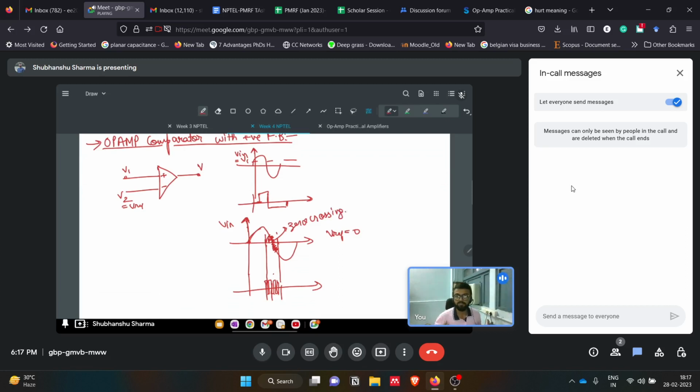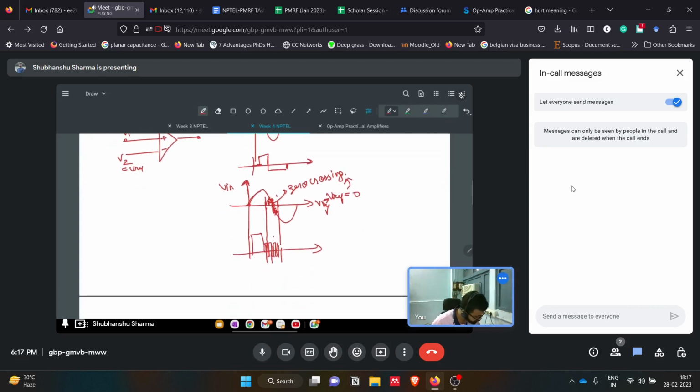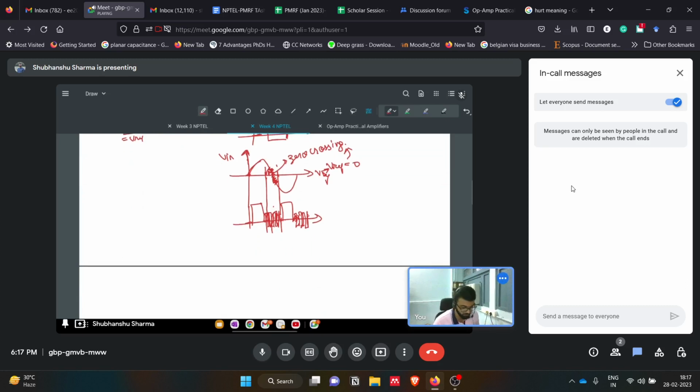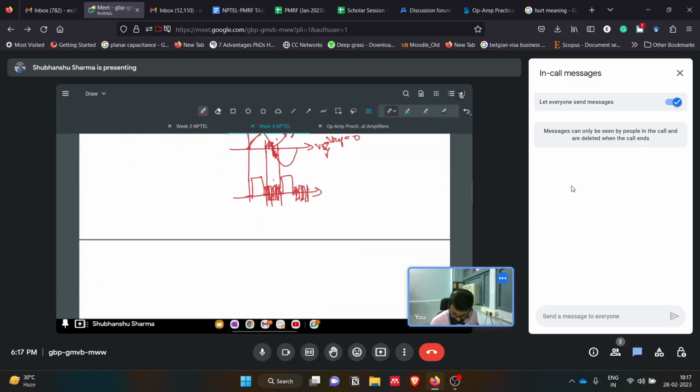We were expecting that at zero crossing there will be no noise, and this signal will be smooth. But instead we saw that, when we set our V reference to zero voltage, there was some noise. The op amp was working nicely, but here it will have fluctuations because of noise. Again it will work nicely, and again at the V reference voltage the output will be fluctuating. So how to avoid this? We can avoid this by setting two thresholds instead of one, and that is achieved by a positive feedback network. We'll see how we can achieve that.